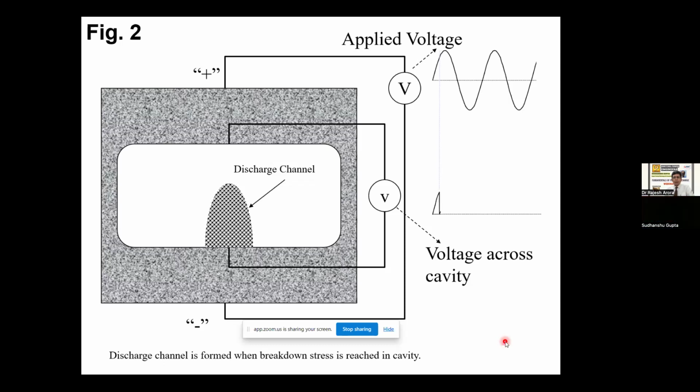That is the reason we have partial discharge levels set in our system. For GIS, it's 5 picocoulomb. For cable, it's 5 picocoulomb. For CTs and CVTs, it's 10 picocoulomb. And for transformers, it's 500 picocoulomb, depending upon the utility. Some utilities ask for 100 picocoulomb. And when it comes to generators, I would say even 5,000 picocoulomb is okay.